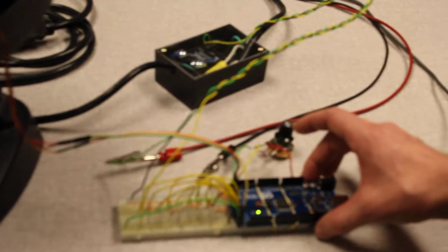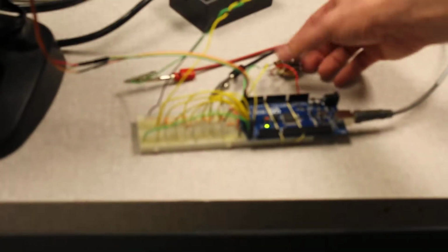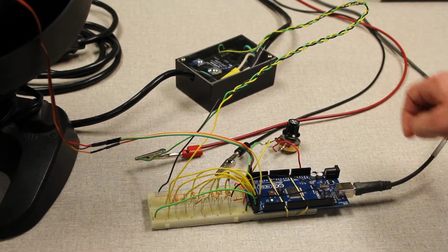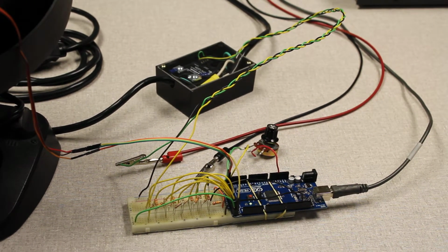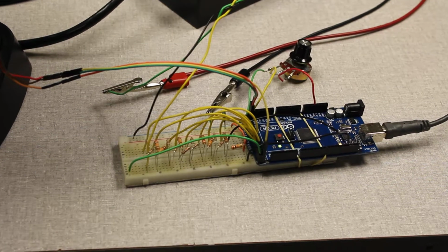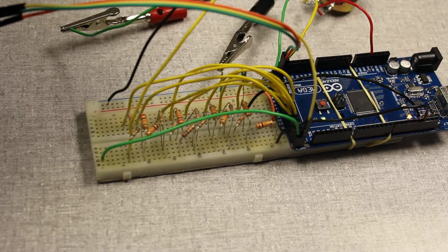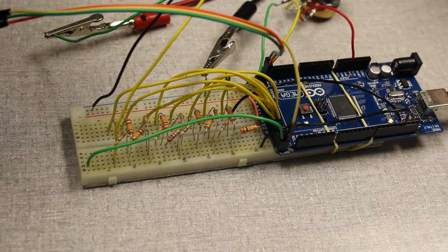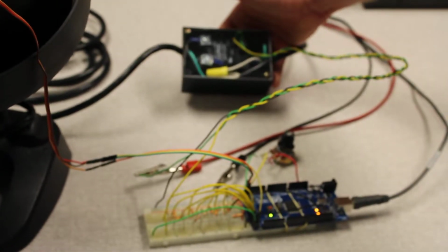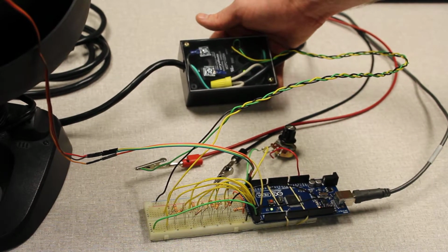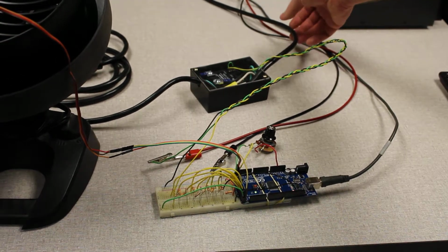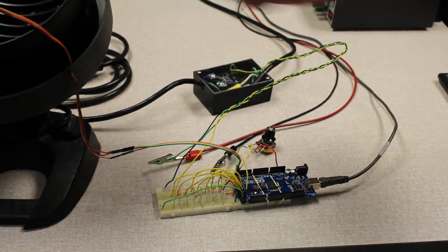The Arduino then compares the set point from a potentiometer and determines an error to be sent out to the digital analog controller in the form of the resistor ladder. The analog signal sent out of the resistor ladder is then fed through to a phase control relay. That phase control relay takes the AC signal from the wall, basically chops the signal up, and sends it back out to the fan to control the speed of the motor.